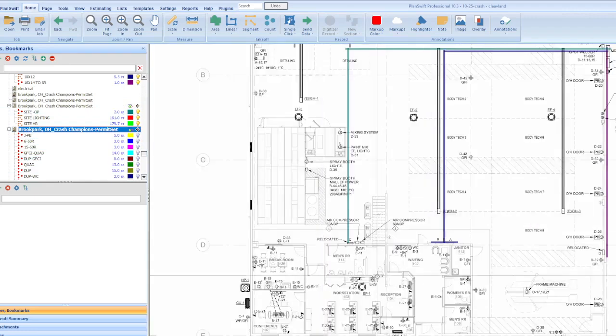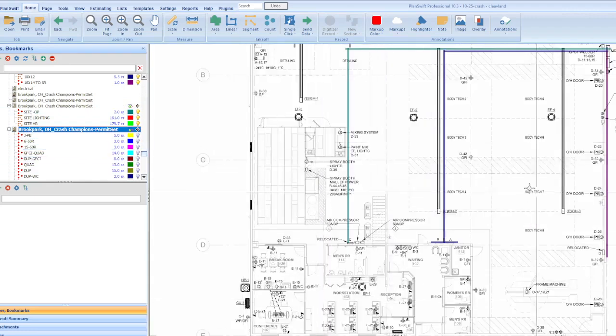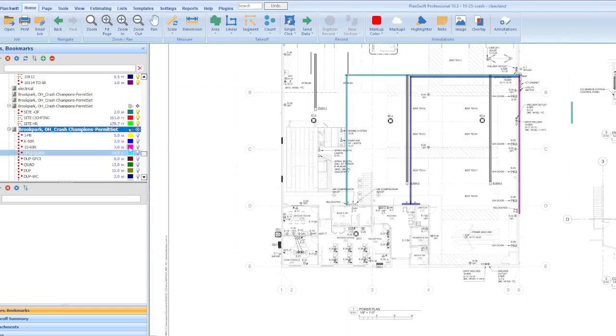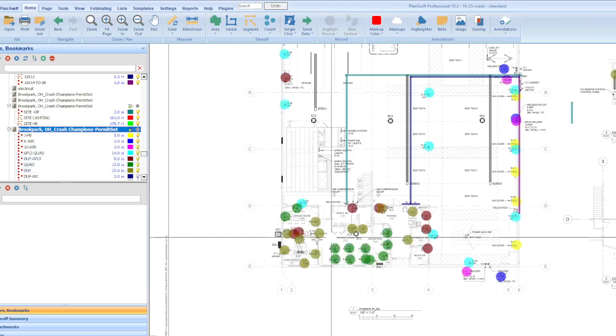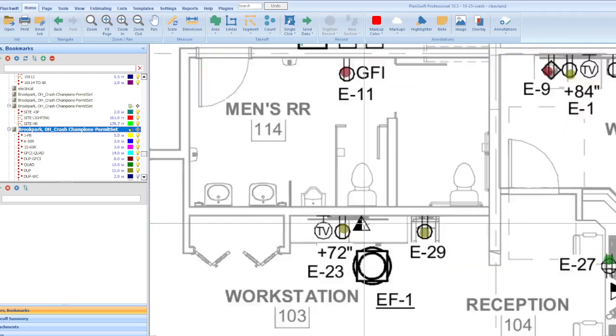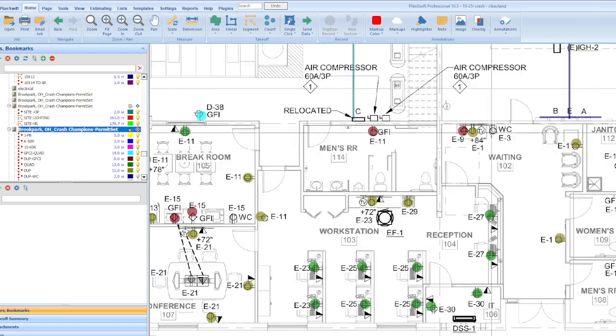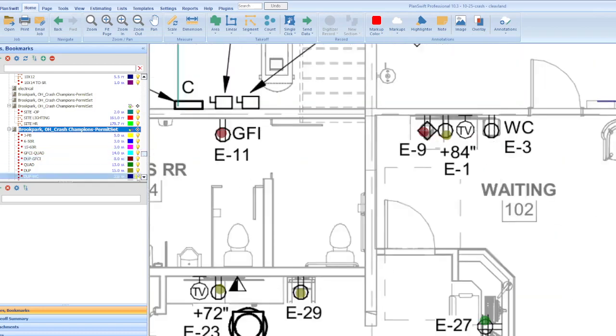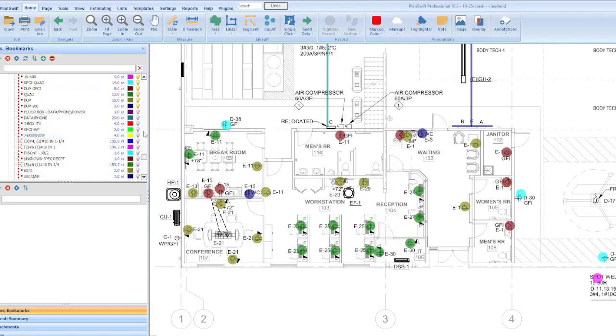But once you win what they consider you, you want to go back with a fine-tooth comb and say, okay, is everything covered? Now, I made everything not covered, so this is our power plan, and these are all of our outlets and all of our everything. Duplex, right? Phone and data, so I know that's a duplex junction box as opposed to a simplex or a single one. Let's see, fill in everything. This had a lot of bubbles. Okay, so good counting tools is critical.